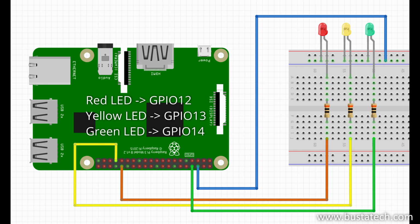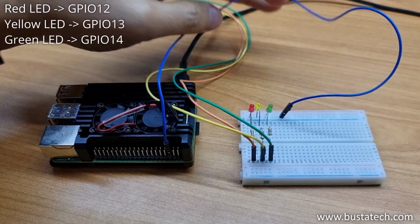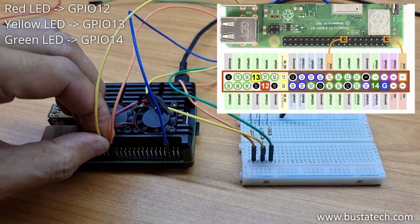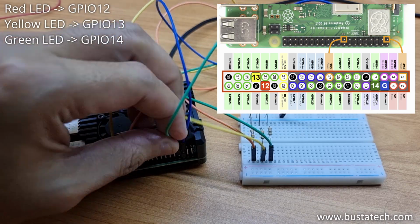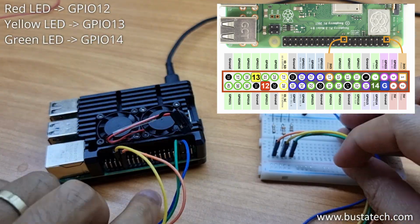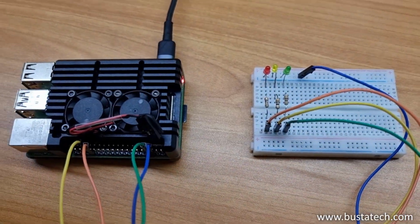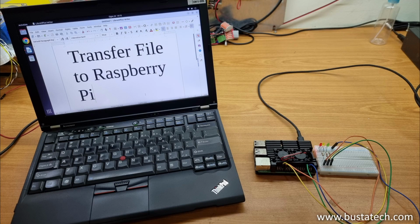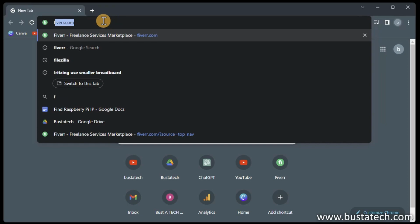Step 3. Connect the ground pin and the LED pins to the Raspberry Pi outputs. Be careful when you plug in the jumper cables to the Raspberry Pi as the Raspberry Pi is turned on. You can also turn off the Raspberry Pi if you prefer that, and turn it back on after your wiring is completed.